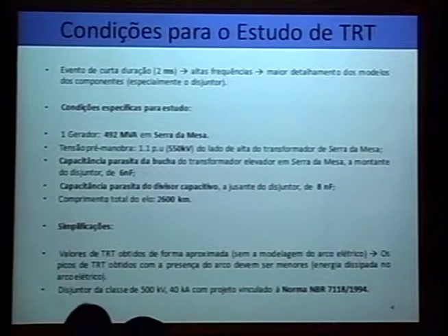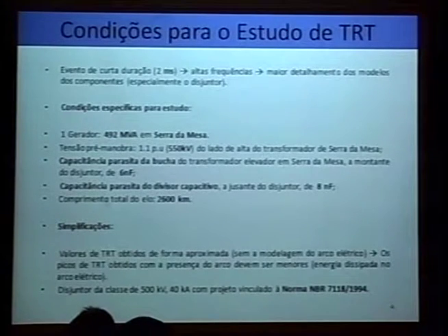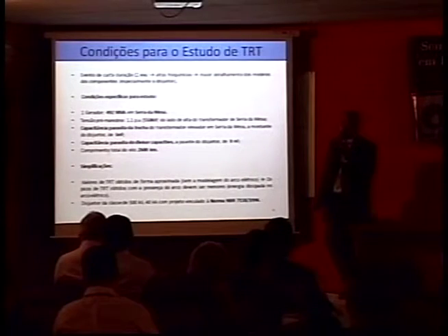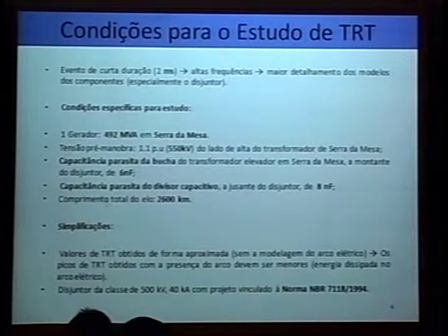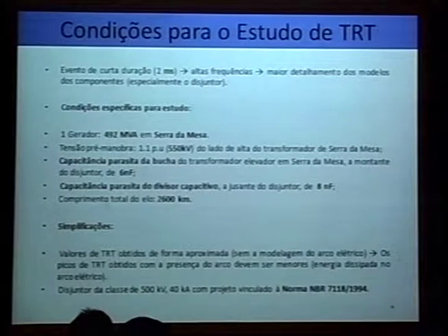The TRV event has a short duration, usually the first 2 milliseconds after the switch is opened. So this involves high frequencies, and automatically you need to have more details of the models for the components, especially for the circuit breaker. Here you have some specific conditions for the study that were used for the test.